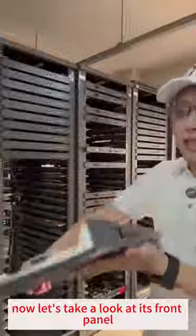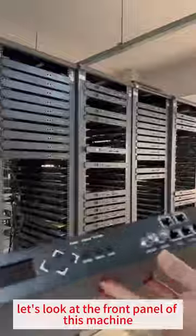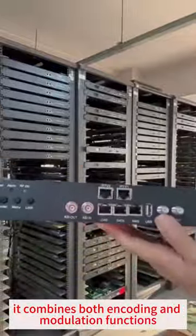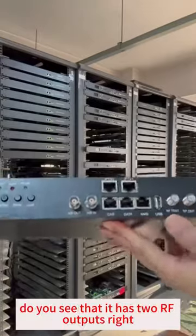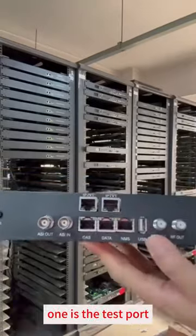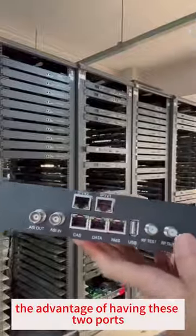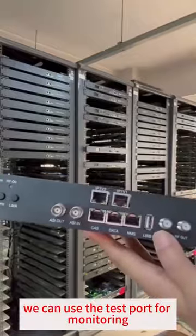Now, let's take a look at its front panel. Let's look at the front panel of this machine. This front panel is called the encoder modulator. As the name suggests, it combines both encoding and modulation functions. Do you see that? It has 2 RF outputs, right? One is the test port and the other is the main output port. The advantage of having these 2 ports is that during debugging, we can use the test port for monitoring.